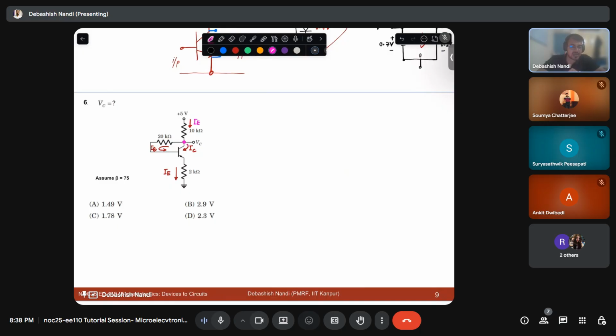So it depends on what kind of feedback I use. This thing is called feedback. What feedback is nothing but a connection between input to output. So depending on what kind of feedback I use, my collector current or the current flowing through the collector resistance may change. Be very careful about that. So now the question is, what is my VC? Fine. To find that out, I need to solve either one of the current, IB, IE or IC. So what is the current that I can solve easily?